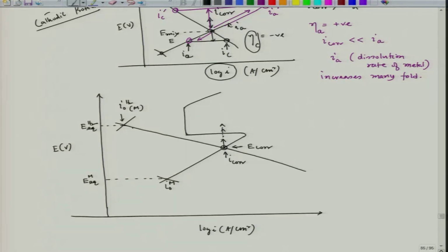If I increase the potential from that E curve, that means the steady state potential, I see that I am gradually increasing the corrosion rate, because I A is gradually moving this way. Finally, it reaches I critical, which is the maximum current density that is possible in this particular situation.